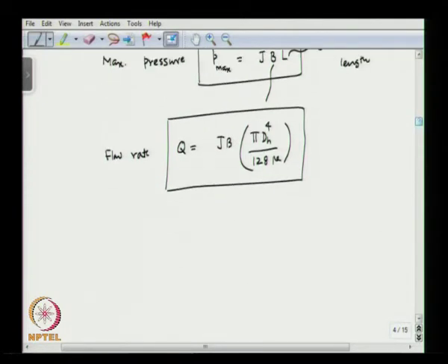So the Lorentz force induces a pressure gradient in the bulk of the fluid. Since it induces a pressure gradient, the flow induced in magnetohydrodynamic effects is parabolic in nature, similar to that encountered in pressure driven flow.